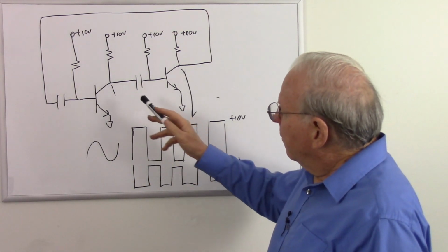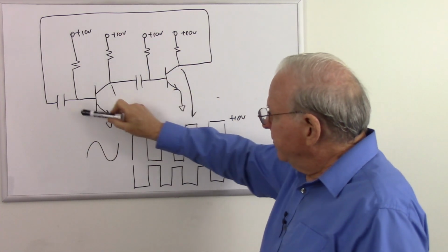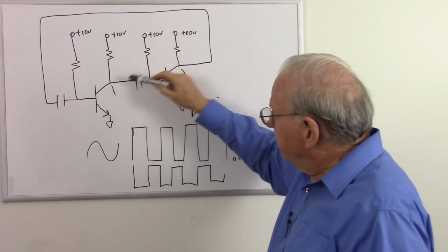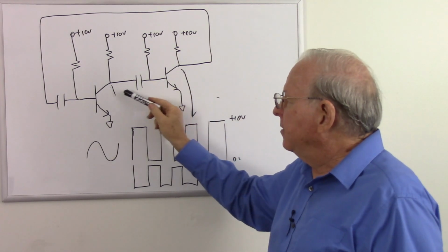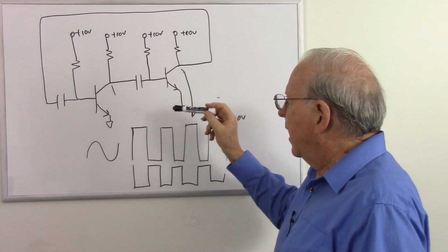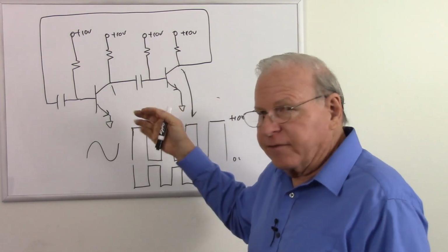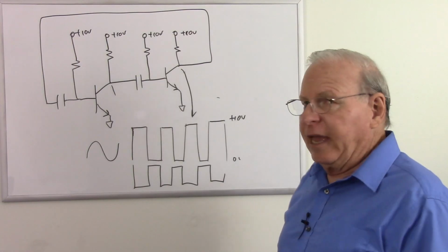So we have what we need. We have amplification. We have feedback. It's positive feedback because of the flipping of the phases. We get our time delay because of the time it takes to charge these capacitors, so it takes time for that to happen. But we don't have any negative feedback, so we don't have the stability we need to make a sine wave